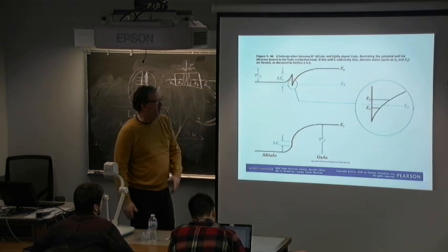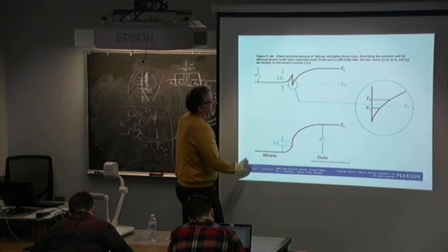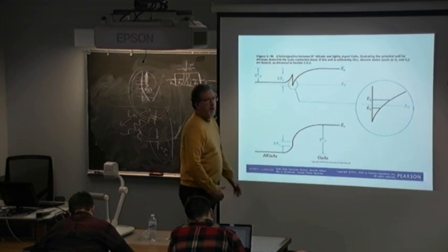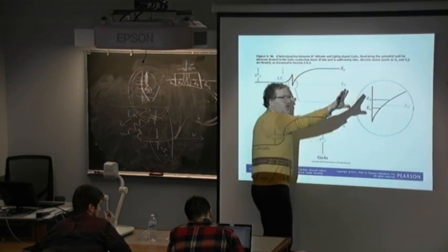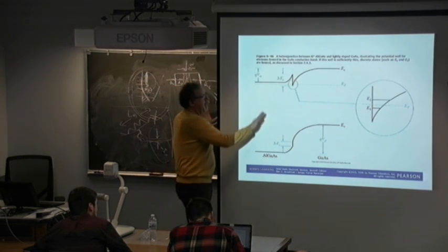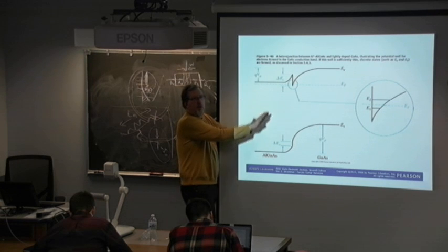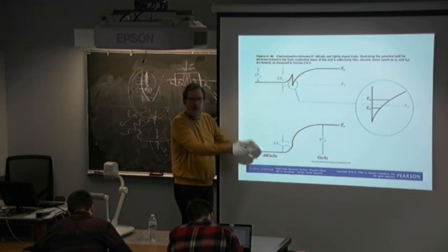So I have a sheet of carriers, and this is where you get the large mobility into the board. So this quantum well is into the board. The source would be here, the drain would be on the back side of the screen, and the gate would be here, pulling this up. It'd be like taking a rug in a hallway.